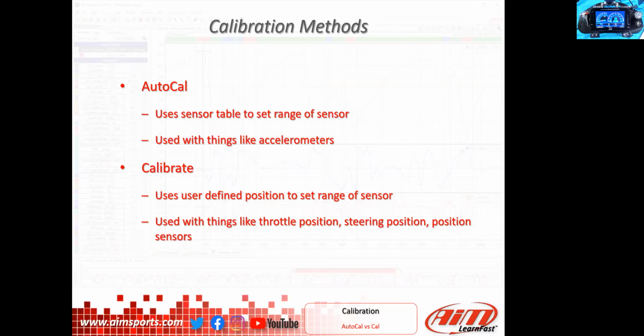But Matt, if you want to chat a little bit about sampling rates, which was one of the questions. Yeah, so sampling rates. A really great question. And there's some generalities, and then a lot of it comes down to what we're looking at. So things like temperature, I look at that and I go, how fast is this temperature really going to change? And if it's an oil temp or an air temp kind of thing, you go, it's not going to change really quick. Like once a second, that's probably fast enough, 1 hertz.